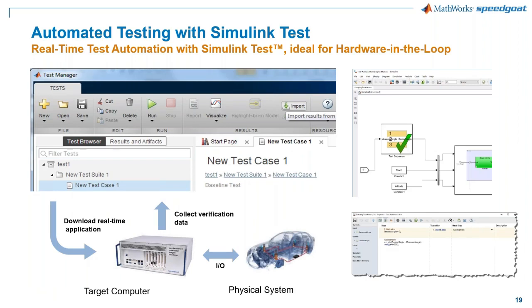Finally, when someone is interested in doing some kind of testing, especially automated testing, they could make use of Simulink Test from the MATLAB Simulink product portfolio, where they can create their tests and then execute them on the target computer, and then see how things are. They can create as many test cases as required, and then automatically run them. So this way, you can author your test cases, monitor the test performance, and finally it generates a report for you to see how your tests are performing. That's a very good way of test automation using Simulink Test.